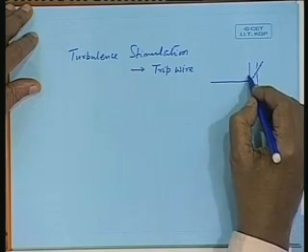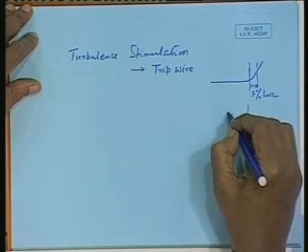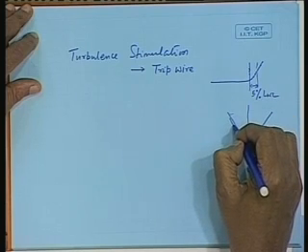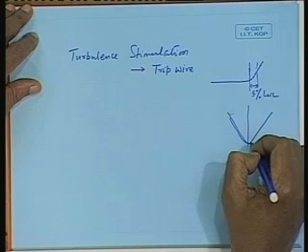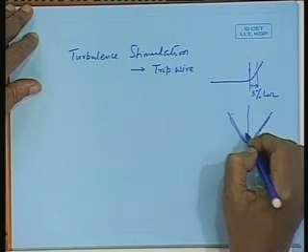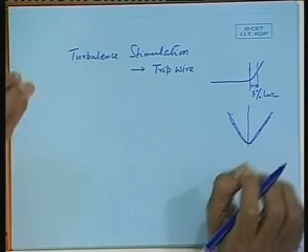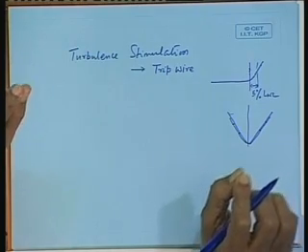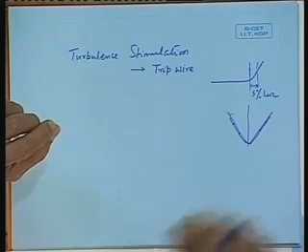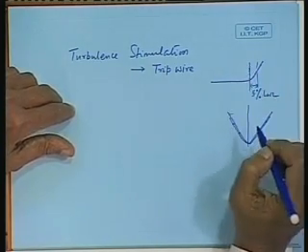So, I can put a trip wire here, that is, if I draw the section here, the section of the ship may be like this. I put a small trip wire all along the model with small anchors holding it by pins. If I have a wax model, I can put pins and hold the trip wire, small pins which will insert themselves into the model.